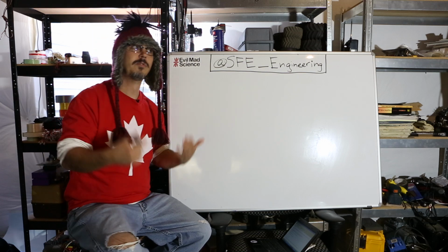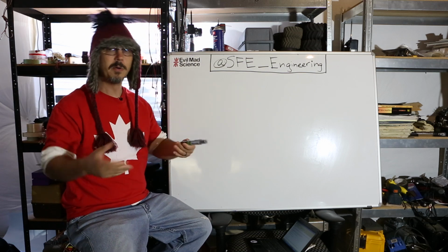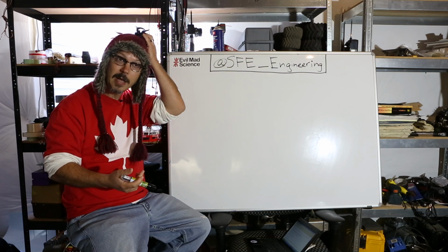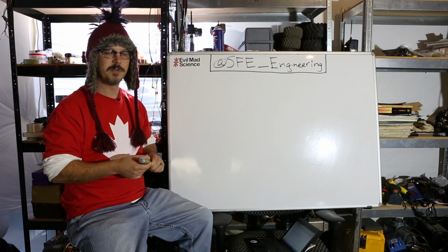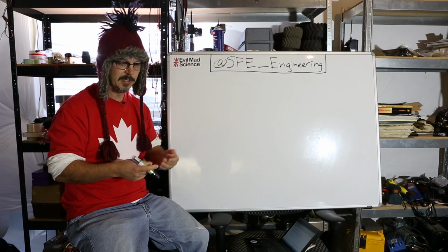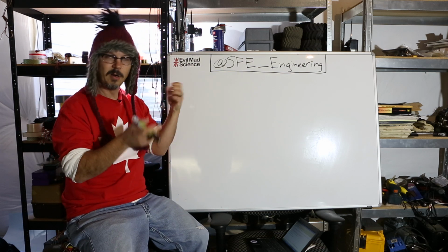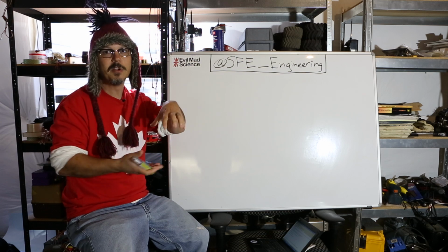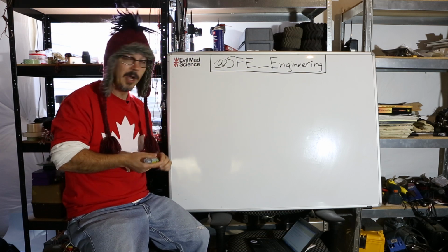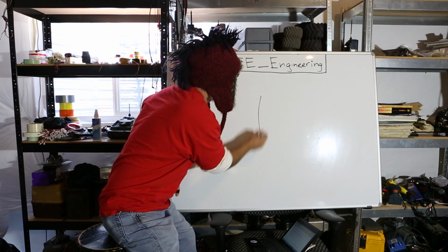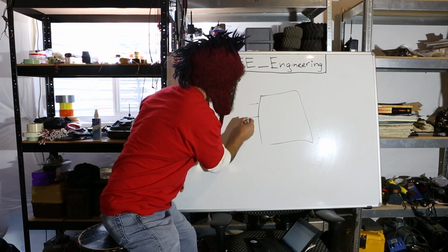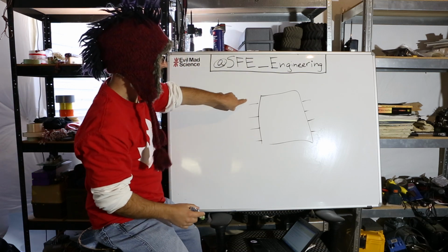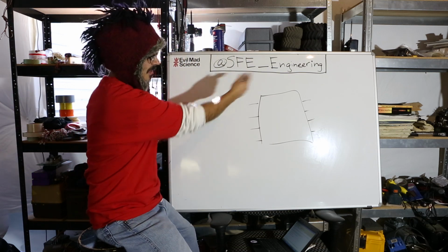As far as the rules of placement for through-hole components and the associated vias, the same rules apply as with what we talked about with surface mount, which is to say that if components are close in a schematic, then they should be physically close to each other on your PCB layout, okay? Now, for example, you've got your op amp here, and if there's a dual op amp, that's going to be an output. These two are going to be inputs.